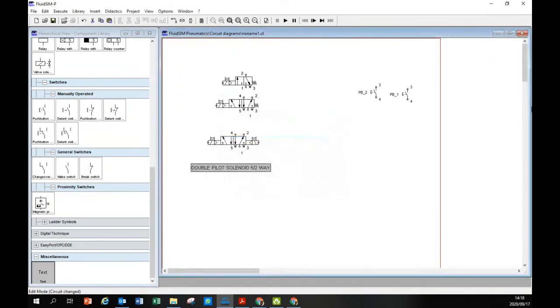5-2-way. I can't make it too long, you'll end up confusing. So this is a double thingy. This one acts with one push button. That one also requires to be actuated only at one point. It returns. On this side is how you actuate it. This side is how it returns, using a spring return.